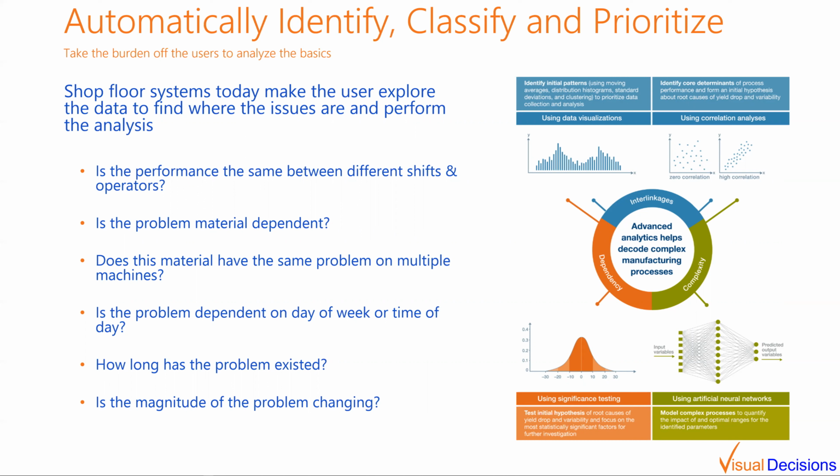And so if you think back to when we were talking about the FMEAs and the probability of detection, and I talked about being able to tie the different signals that we're trying to collect from the machine to those different failure modes, the goal here is to be able to identify what are those signals that are going to be able to tell us when a particular failure mode is occurring.